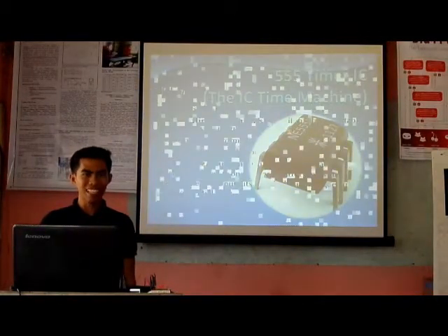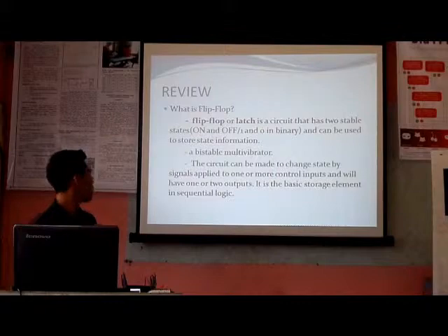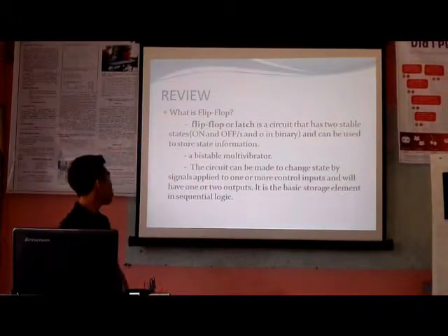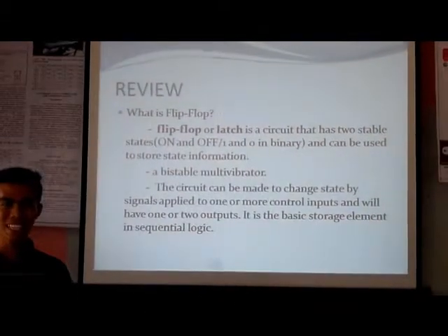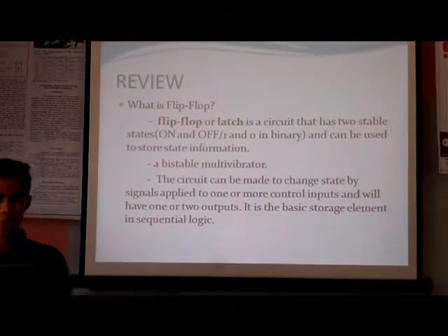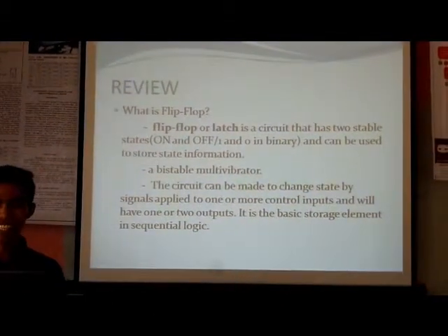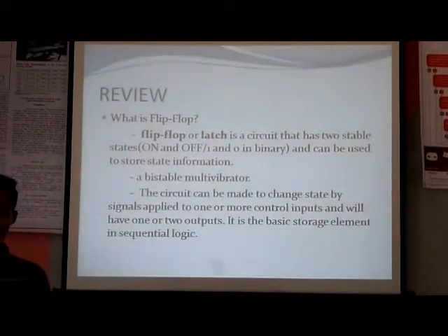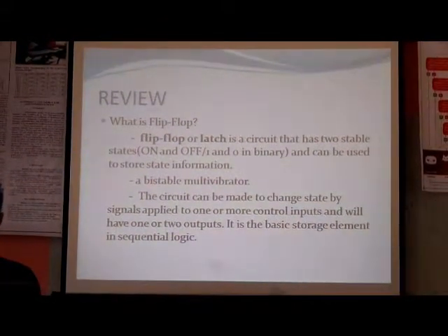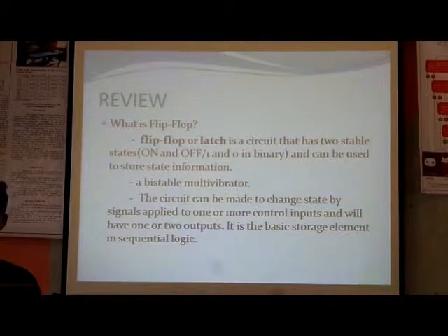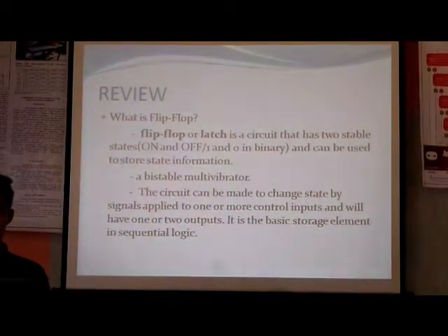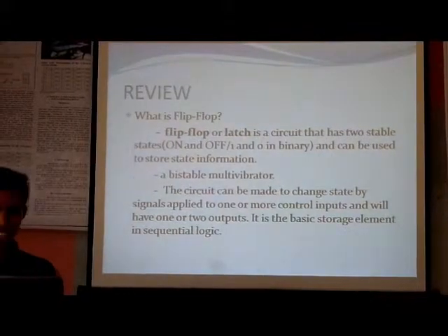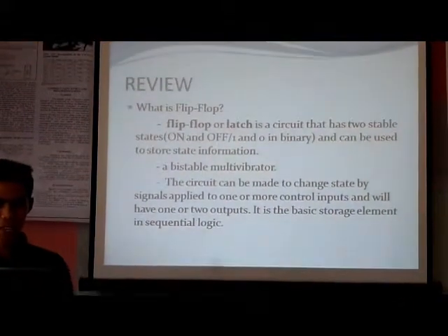But before that, let's review first our previous topic. Our previous topic is all about flip-flop. So what is a flip-flop? A flip-flop, or what we call a latch, is a circuit that has two stable states, on and off, 1 and 0 in binary, and it can be used to store state information. And a flip-flop is a bistable multivibrator.